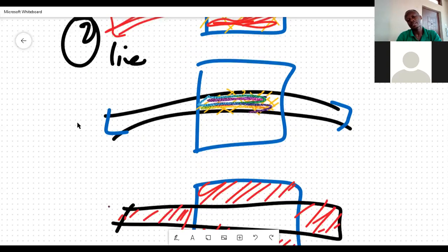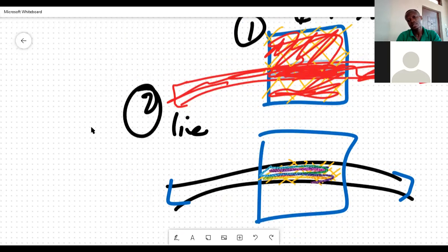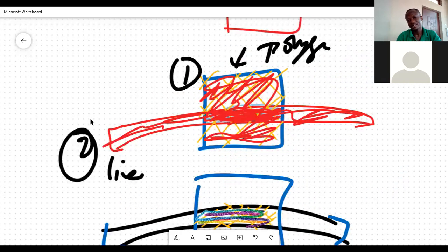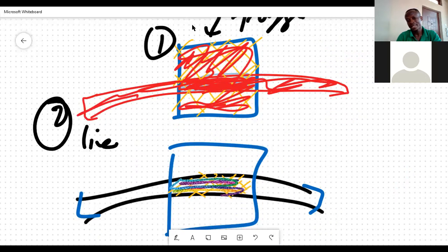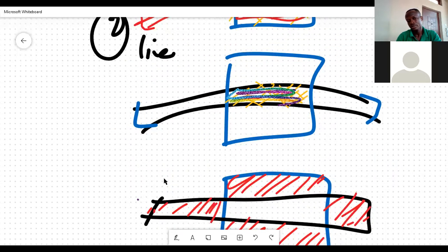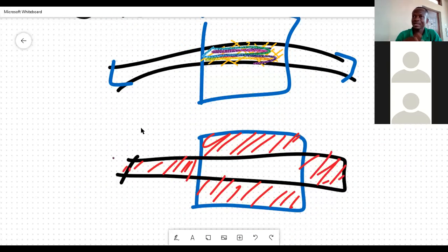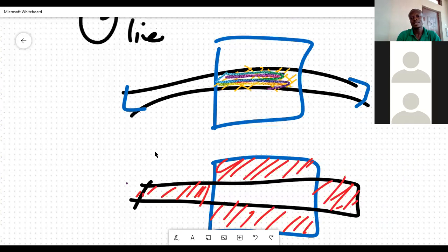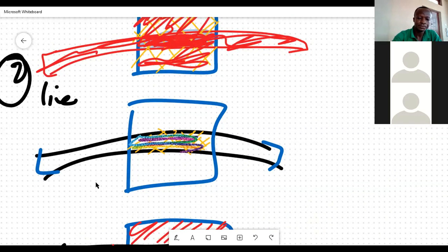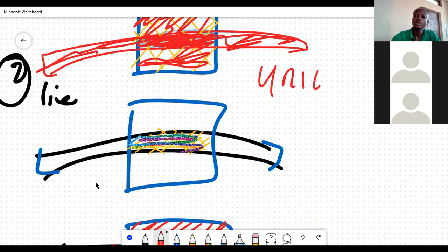You understand the example I've given to explain the combination of data sets. It's a combination of what data sets? Data set one is linear, something like lines. The data set two is sort of polygons, and we just want to overlay and see which areas are of interest. Do you understand the union overlay? This one is a union. Overlay. This is the intersect.